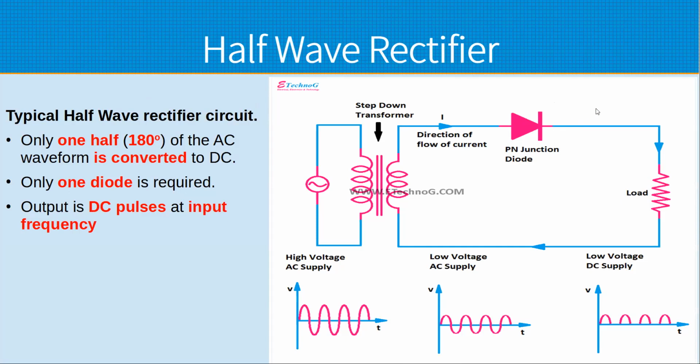In the olden days, they used to make special components that were used as rectifiers. Some of them were a stack of selenium plates that only conducted one way and handled a lot of power. There were some other forms of them. Now, they're almost always a solid state diode. Bridge rectifier with big heat sinks on it.